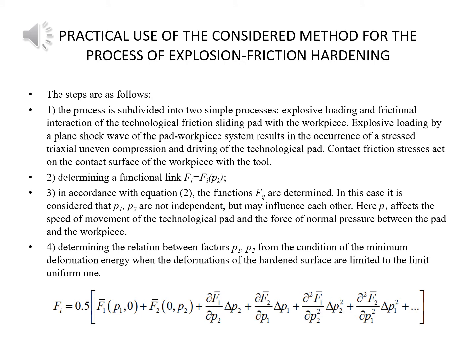The steps are as follows. First one, the process is subdivided into two simple processes: explosive loading and frictional interaction of the technological friction sliding pad with the workpiece. Explosive loading by applying a shock wave to the pad-workpiece system results in the occurrence of a stressed triaxial uneven compression and driving of the technological pad. Contact friction stresses act on the contact surface of the workpiece with the tool.